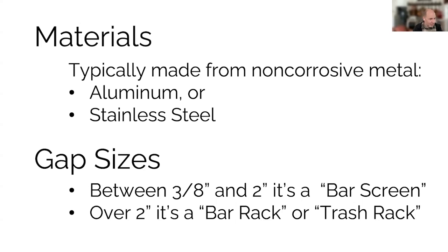You are not going to really have bar screens with gaps smaller than 3/8 of an inch because they would plug up too quickly and potentially cause overflows. Typically, bar screens have a couple of channels so that you can balance the flow, but not always. And sometimes you'll want to be able to take one channel out of operation while the other one is still functioning so that you can clean them.